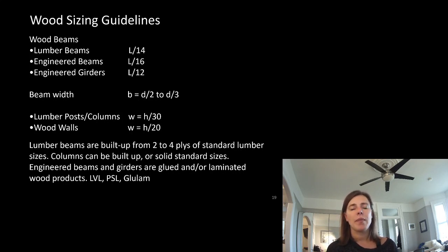I hate the beam width sizing guidelines because people get hung up on them. This is more just an intent to help you figure out roughly how many plies you're going to need here. And it kind of gets annoying. If it was a 2x8, are we using the 8-inch deep, or are we using the 7.5 inches deep? Yeah, it's a sizing guideline. It is a rough approximation of the answer.